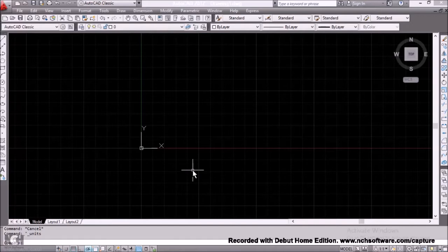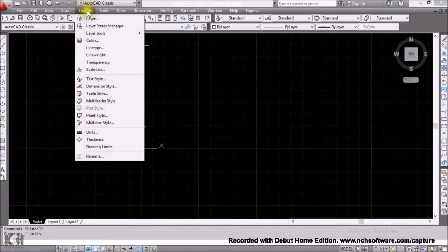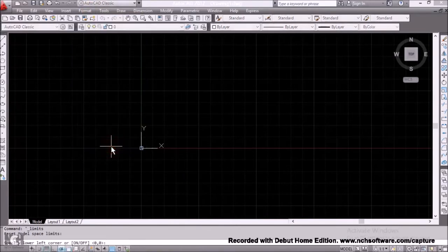But if you want to set up your first workspace and you have an intention of the workspace accommodating numerous designs, okay, so many designs, that means you have to set a very large workspace. So how do you set your workspace in AutoCAD? To set your workspace in AutoCAD, you still locate the format icon on the menu bar, and then you click on drawing limits. If you click on drawing limits, you go to your command line.